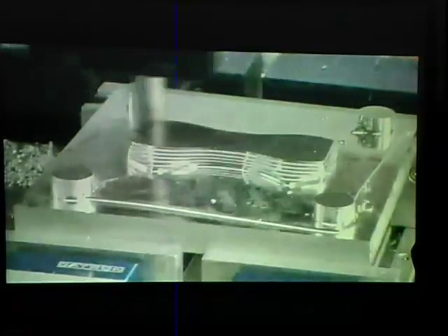This is a very precise, very accurate machine. It's probably working in the 10,000ths of an inch. As you step down, it's moving in the X and the Y. Then it's going to go ahead and step down and make another layer in the Z. We make multiple layers in the Z. And I, as the operator, as the person doing the programming, am able to select how it does this, what type of cutting tool I'm using, the RPM of the machine, the speed rate of the machine.